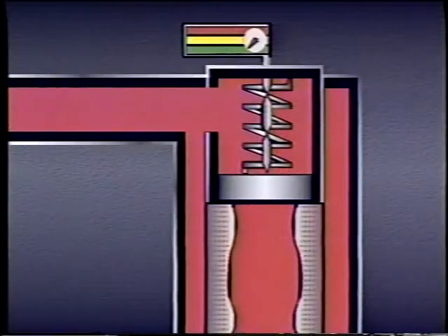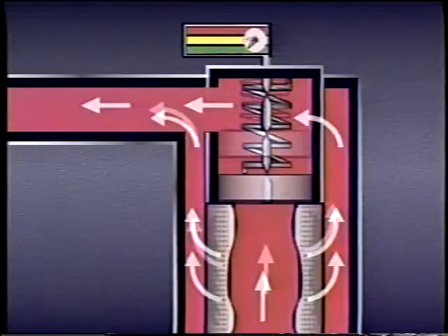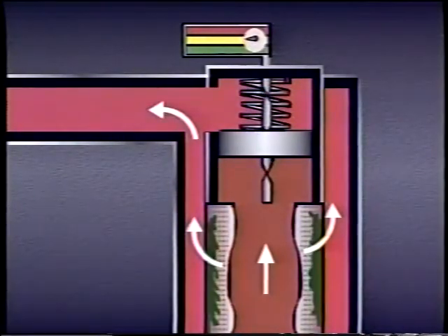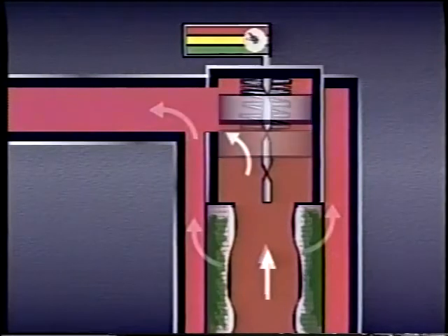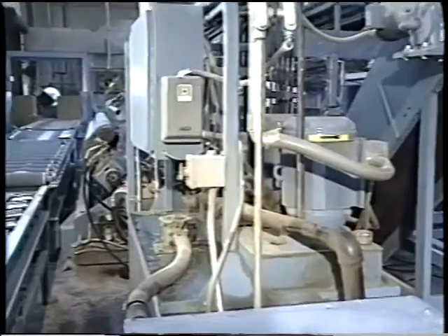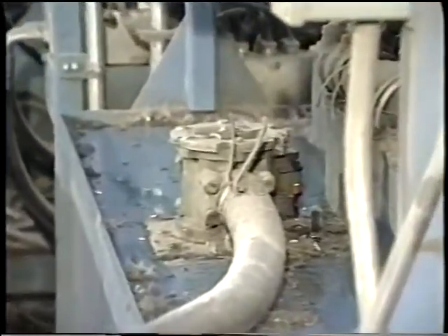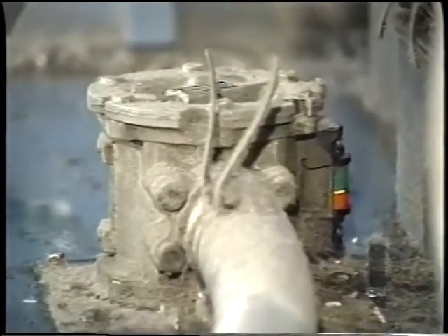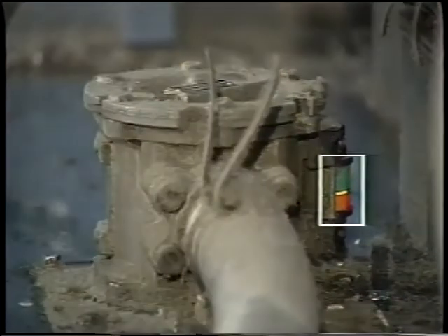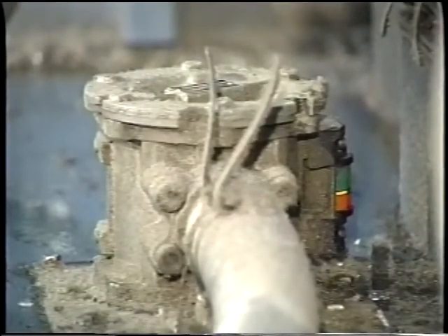As the filter gets dirty, the pressure differential across the filter becomes larger. As the piston moves up, it compresses the spring. When the differential is great enough, the piston moves up far enough to allow all the fluid to bypass the filter. These filters will continue to bypass fluid until the element is cleaned or replaced. Filters usually have indicators which show at a glance whether the element is clean, dirty, bypassing, or missing. A filter should be cleaned or changed when its indicator says it is dirty. Filters allowed to bypass hydraulic fluid permit contaminants to build up.